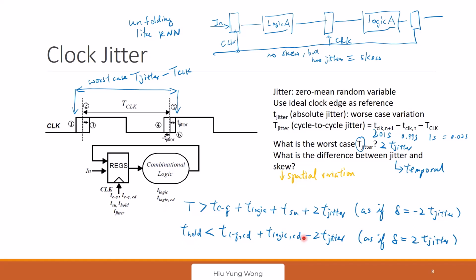So no matter what, when you come with a random variable in the future, you design different things. Just like when you design a circuit, people talk about the corner. We don't have corner design in this class, but you learn that in E223. You do a lot of corners. You try to see fast, slow, or slow, fast. Usually you don't care about those if both NMOS and PMOS, but they can be the worst case actually. But let's say both are slow, both are fast. It can happen that the PMOS is faster, but we always look at the worst case, just like here. Any questions?